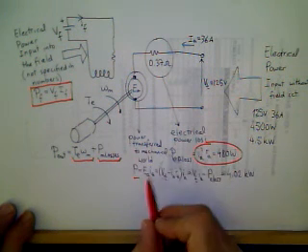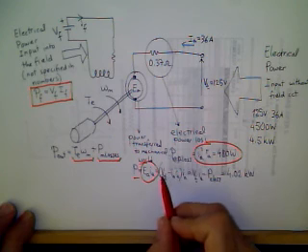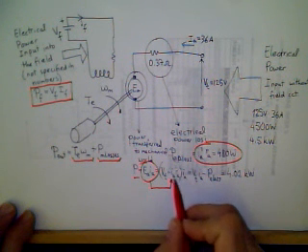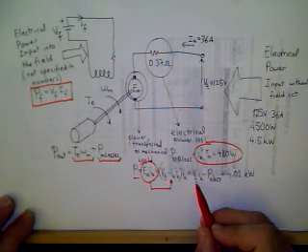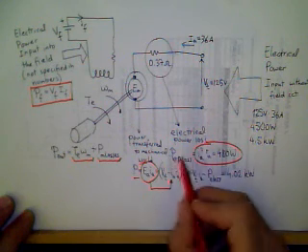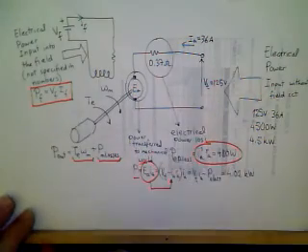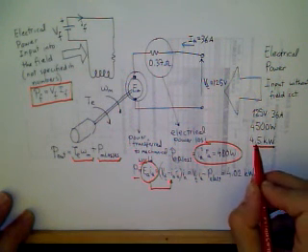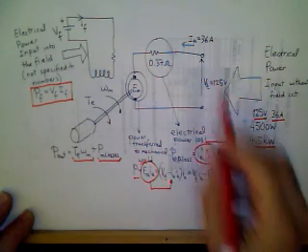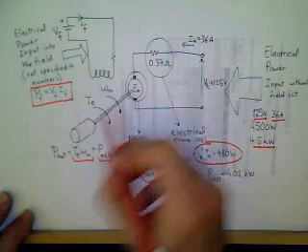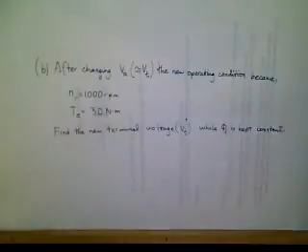This power, the electrical power input to the system, is E sub A, I sub A, and we substitute Vt minus Ia Ra into Ea and write Ia. So Vt times Ia minus that power loss on the resistor results in 4.02 kilowatts at this point. So the electrical power input to the system is 4.5 kilowatts because we know the terminal voltage and current, and some power is lost here. Net power converted towards mechanical is 4.02 kilowatts in this motor.